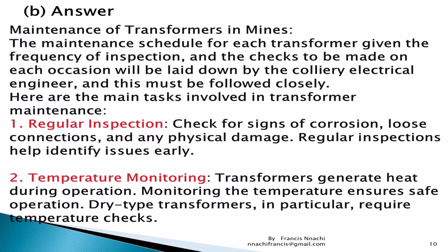So regular inspections will help identify issues earlier. Then temperature monitoring. We have to monitor the temperature. Transformer generates heat during operation. So monitoring the temperature ensures safe operation.